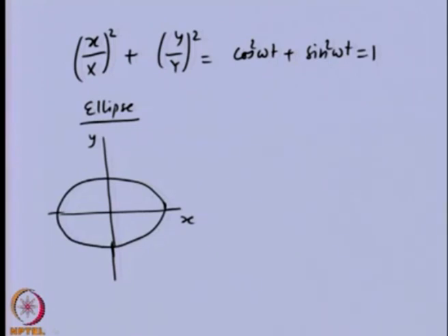The rotor center will be moving during the whirling. So, during whirling, this will be the orbit, where this distance is the capital X and this is the capital Y. And this ellipse orientation will be along the x and y direction.